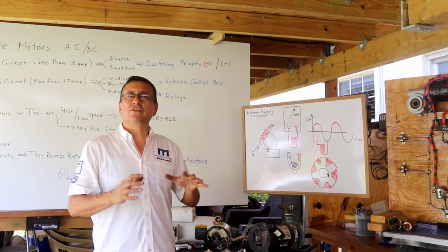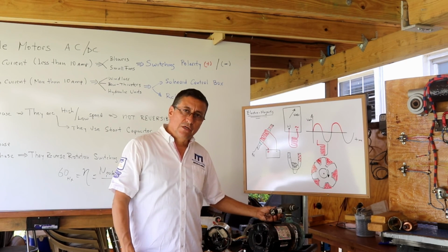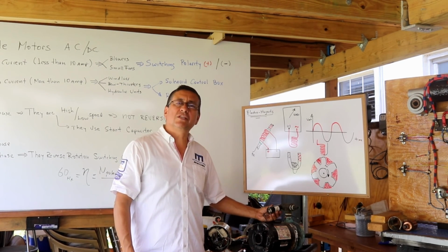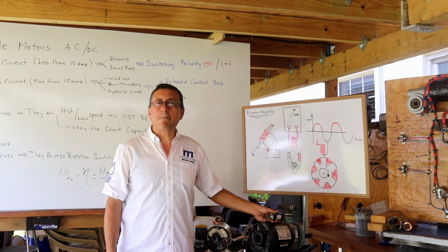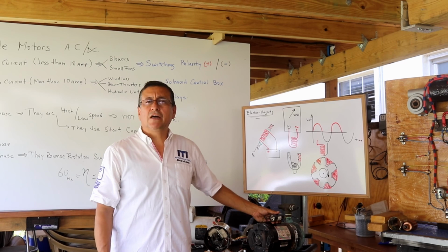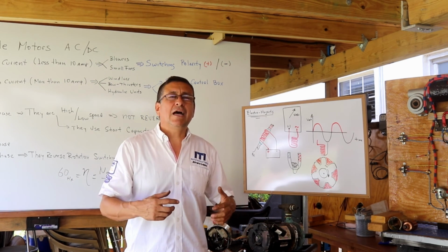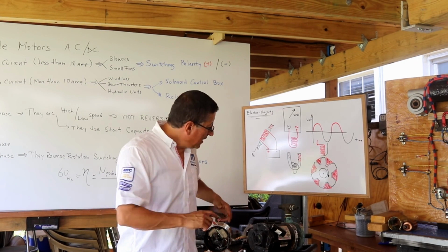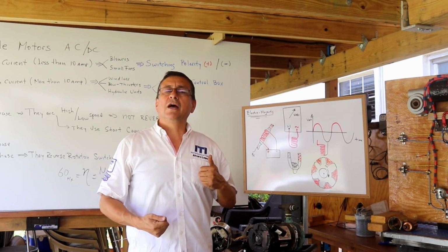All single-phase AC motors have a start capacitor, and the capacitor is used only to start. What is the symptom when the start capacitor in a motor is damaged? The symptom is that the motor is humming and it's difficult to start. Probably if you help with your hand on the pulley, the motor continues running.